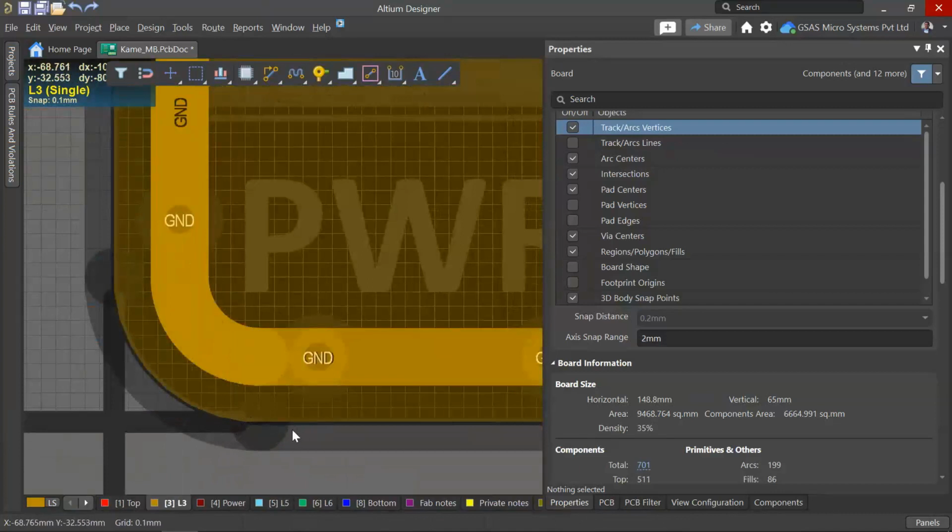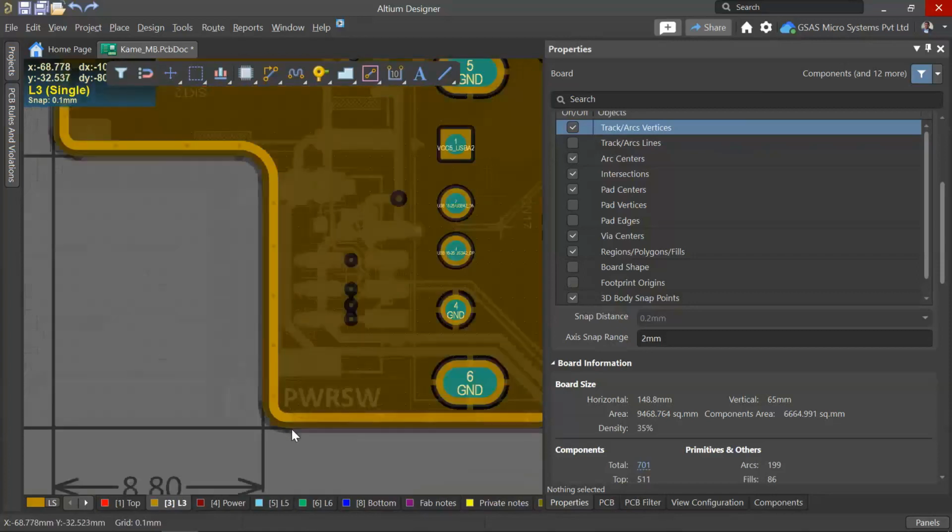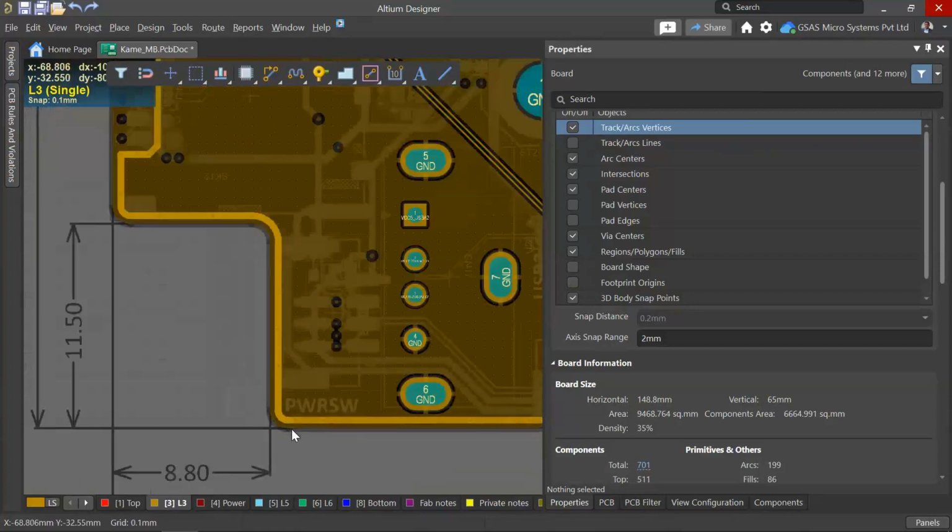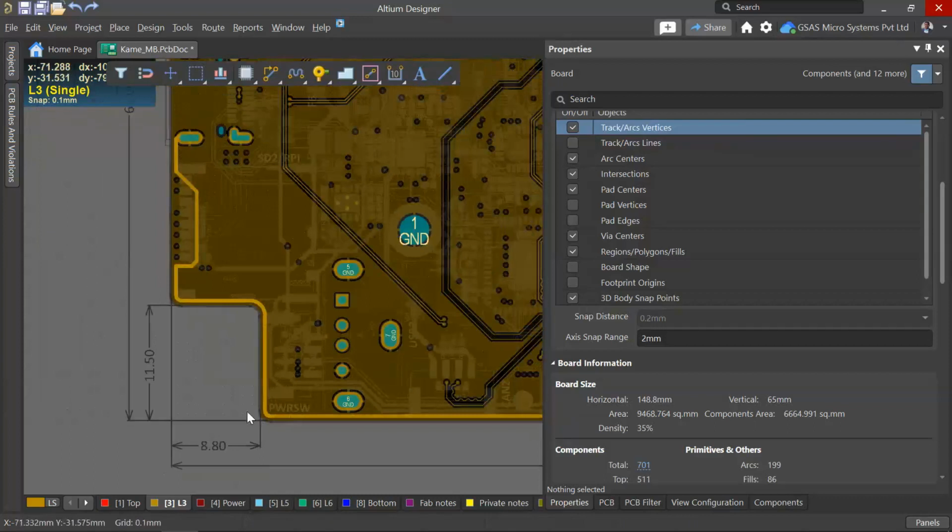towards the board edge. During the fabrication it may get open and it may get in touch with any metal object where your PCB gets inserted, and it may create a problem. We need to maintain a sufficient amount of clearance from the board edges. Okay, for that you have to set the design rule.